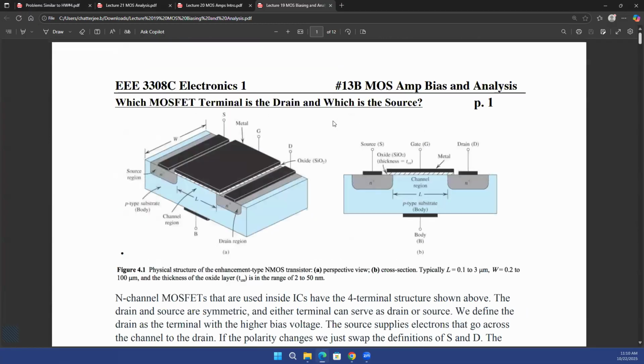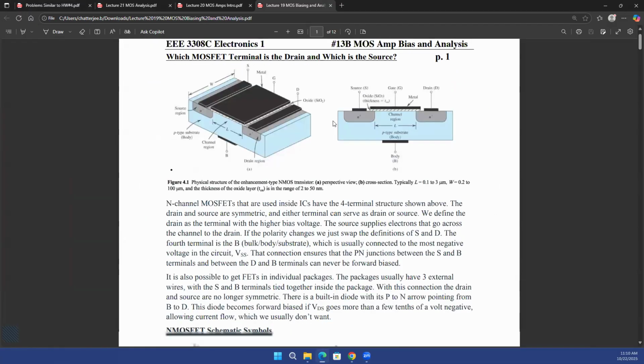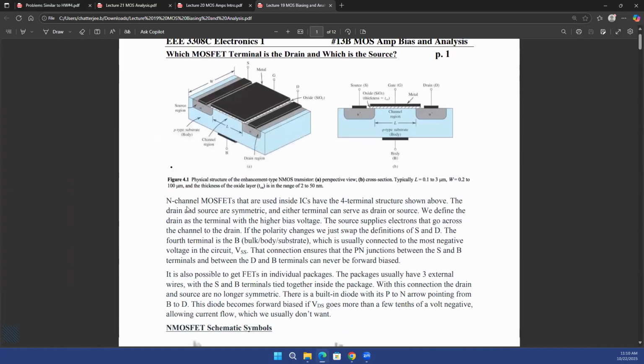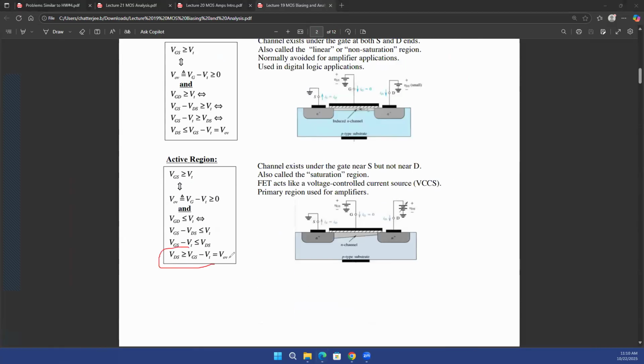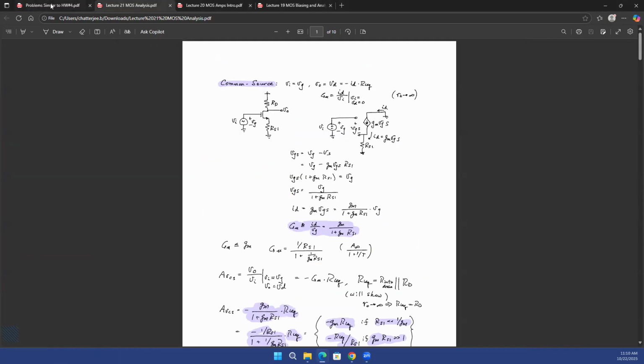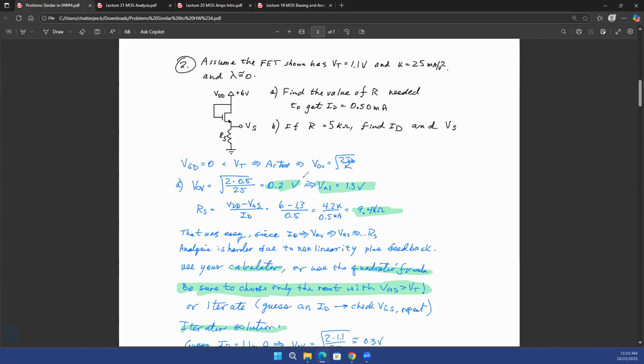so what here, when we were discussing these MOSFETs for the first time, we discussed all these equations, right? When you are in the active region or in the saturation region, you basically say your VDS is greater than V over drive, but that can also be represented as VGD less than or equal to VT. So both of them mean the same thing because these are just mathematical manipulations. So by using that same formula, VGD is lower than VT, you know that the transistor is in the active region.